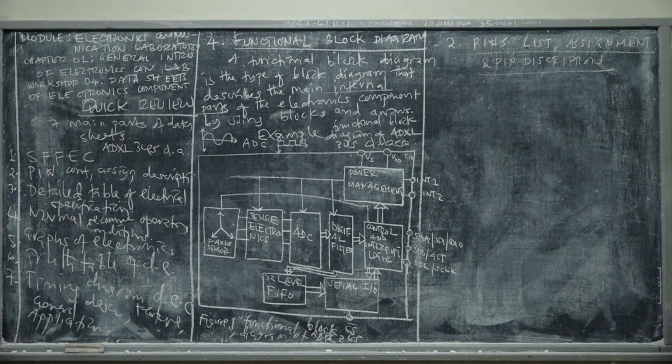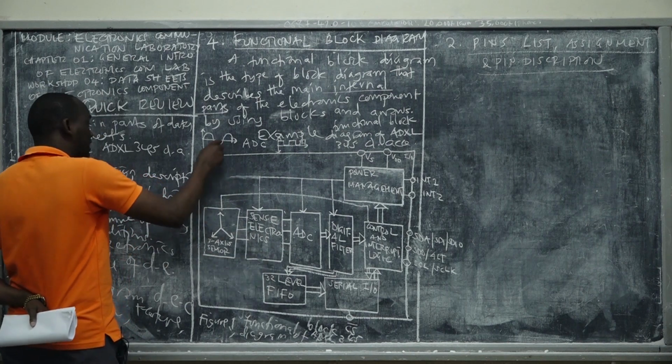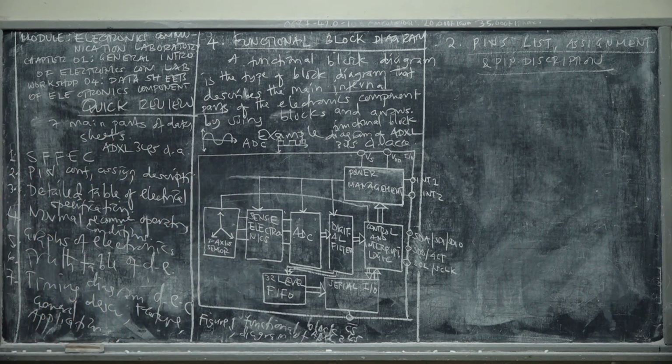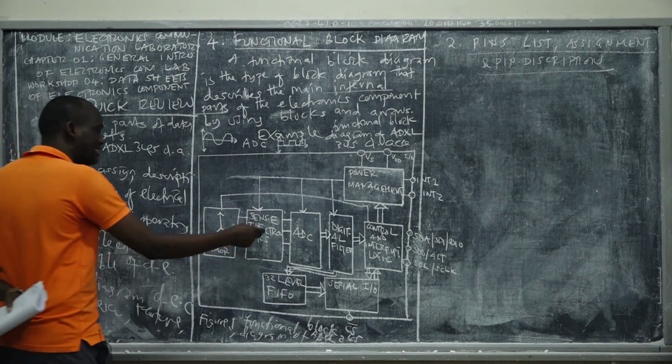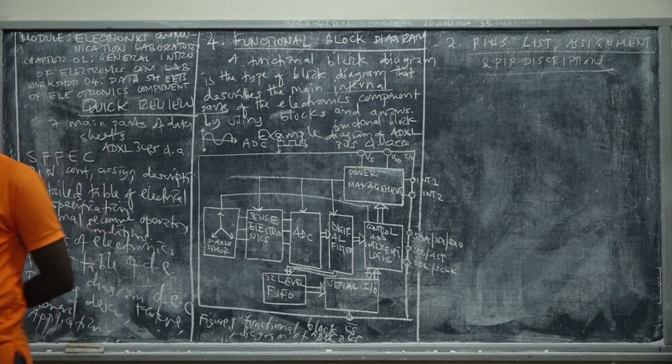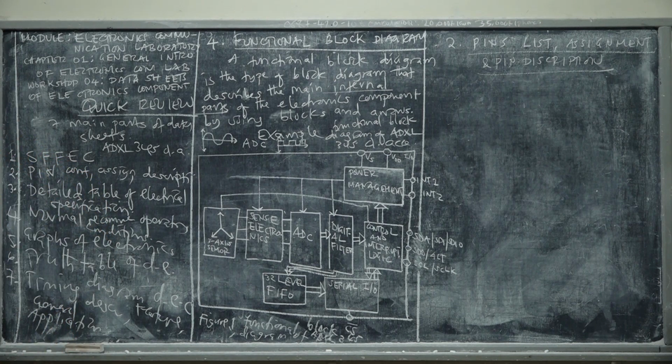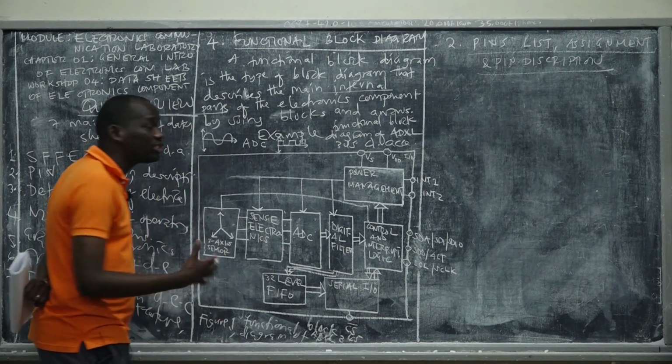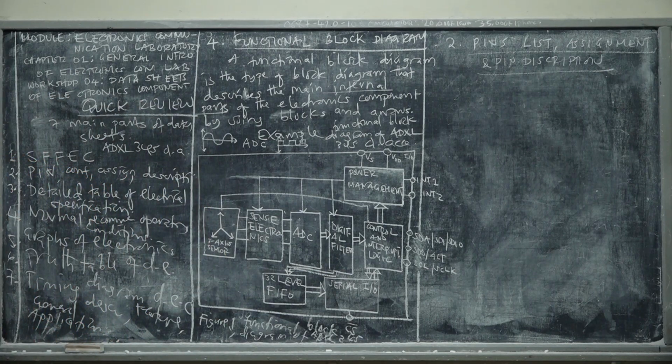So the analog to digital converter will focus on voltage, but currents can also be converted, because the logic signal has only 2 states, high and low. But the main focus is voltage. And remember that the voltage given out from this sensor is in millivolts, very small. That's why we need other blocks to process that signal before delivering it to the next part, the control of your system.